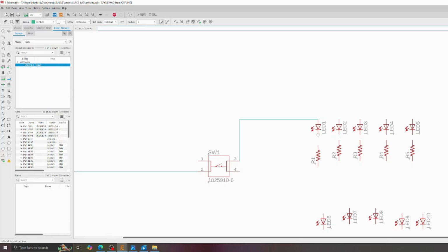And for this, I know it doesn't tell you anode or cathode, but you could easily just search up schematic LED symbol and it'll tell you which side is positive. But I could tell you right now that the one with the triangle's bottom is positive. So we're going to take all that and connect each one. One thing that I like about Eagle is you don't have to click on each one individually. If you just go all the way to the back, it'll connect all of them.